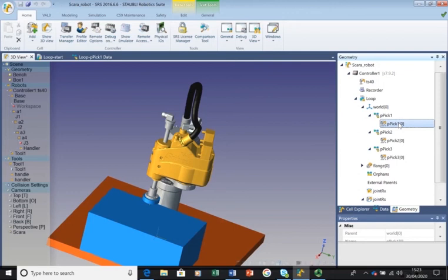What you can do then is, with these real-world coordinates, use the transfer manager and get them back off the robot, and then you'd have the real-world data matched, and you can sync up the Stäubli software with the real robot. As such, when the robot moves, you'd see the simulation move at the same time, driven by the robot, which sometimes can help you.